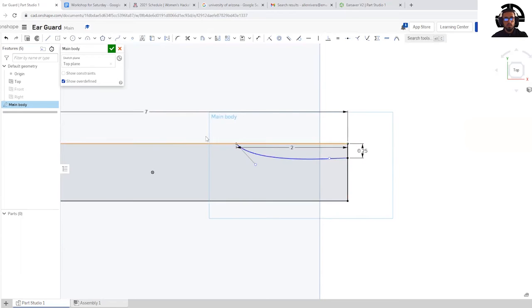Well, Onshape includes a very, very unique way of allowing you to mirror the object. So basically all I have to do is create a line. I prefer construction lines because they're very minimal and you do not see them when you exit out of the sketch. So I'm going to go from the origin. I set that point and I'm going to go up across the y-axis straight. It doesn't matter the length. And I'm going to hit escape.